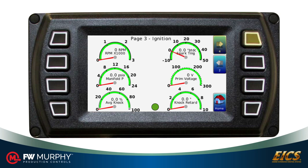Screen 3 shows ignition information. Again, we show RPMs. Also shown is ignition timing as the engine is operating, manifold pressure, primary coil voltage, engine knock if the engine is set up with detonation detection or knock detection, and the knock retard.